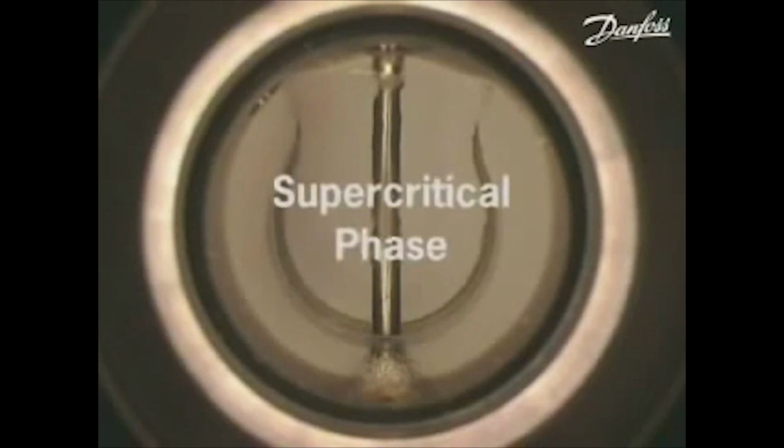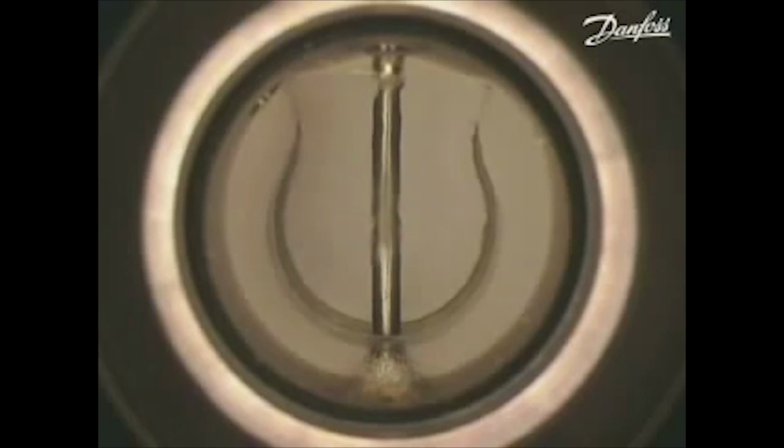This supercritical CO2 has some interesting and user-friendly properties. Its high density gives it some of the properties of a liquid, so for example, it can act as a solvent for extracting various materials. However, its viscosity is much lower than for most liquids, and its diffusivity is consequently higher. These properties have led to a great deal of interest in the use of supercritical CO2 as a safe, effective solvent, in particular for food products.